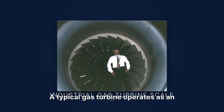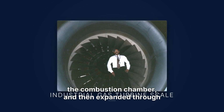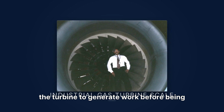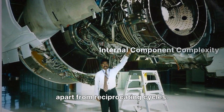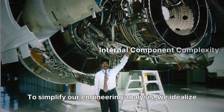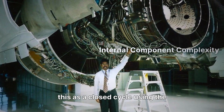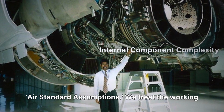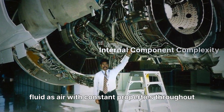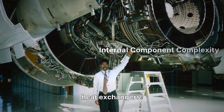A typical gas turbine operates as an open system where fresh air is drawn into the compressor, mixed with fuel in the combustion chamber, and then expanded through the turbine to generate work before being exhausted. This continuous flow is what sets it apart from reciprocating cycles. To simplify our engineering analysis, we idealize this as a closed cycle using the air standard assumptions. We treat the working fluid as air with constant properties throughout and replace the complex combustion processes with heat exchangers.